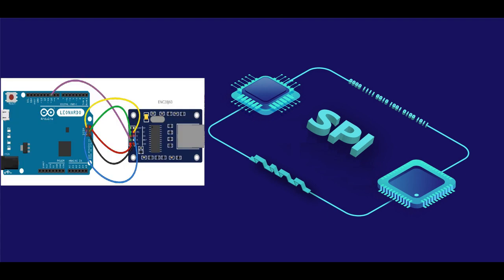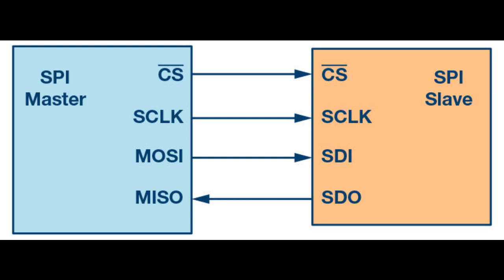Electronic devices talk to each other by sending bits of data through wires physically connected between devices. A bit is like a letter in a word, except instead of the 26 letters in the English alphabet, a bit is binary and can only be a 1 or 0. Bits are transferred from one device to another by quick changes in voltage. In a system operating at 5 volts, a 0 bit is communicated as a short pulse of 0 volts, and a 1 bit is communicated by a short pulse of 5 volts.